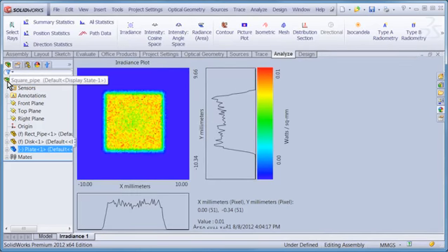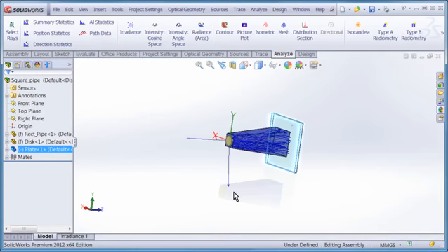And here's the data. Now, at first glance, we can see that this looks relatively uniform. We can certainly see that the irradiance is a bit lower towards the center, and that's simply because with the cross-sectional changes in this light pipe, we really haven't traveled long enough to get a nice uniform distribution of the energy after we propagate through the light pipe. It's important when doing light pipe analysis that your light pipe section is long enough to fully homogenize the beam so your light pipe represents the real physics of your simulation.